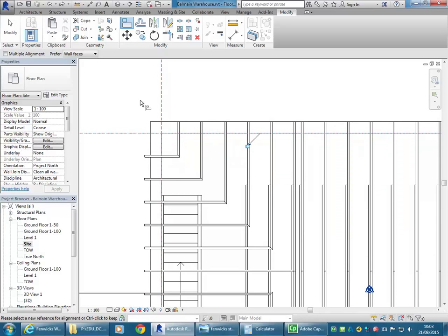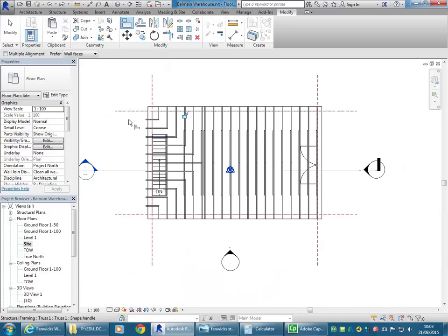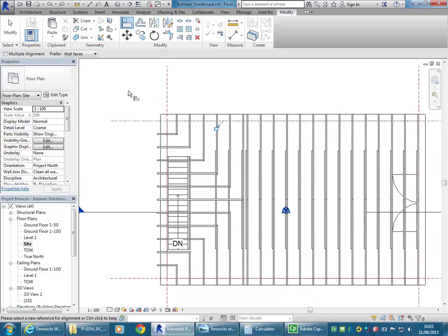That's a really useful tool for adjusting things. Align, just above the move button. Reference plane first, and then the inside face of the wall, the bottom of that wall that you want to move. Accurate way.